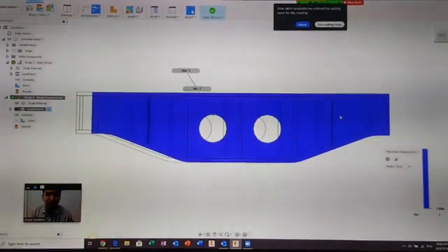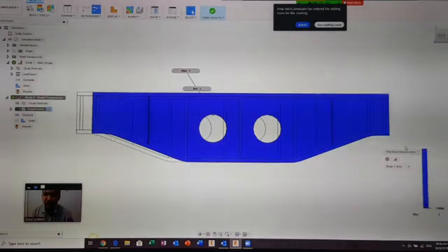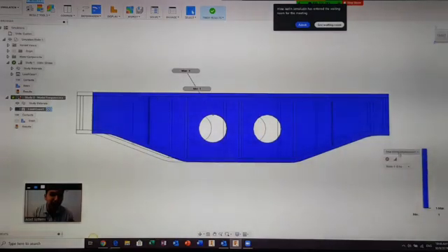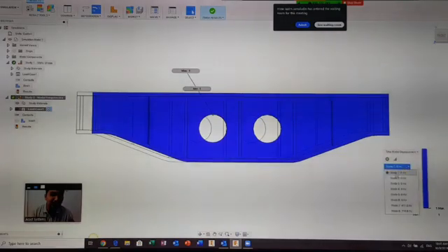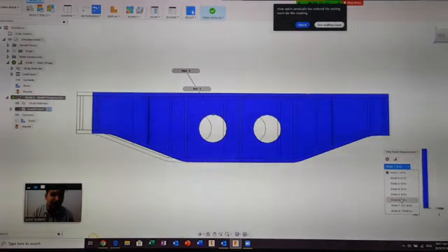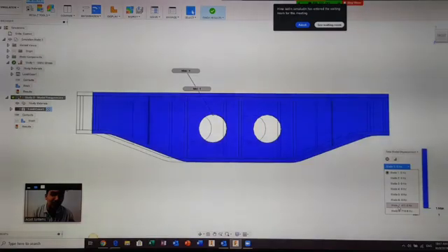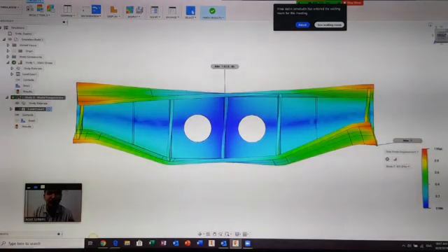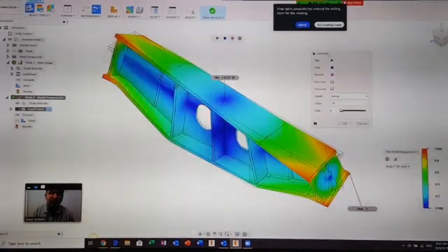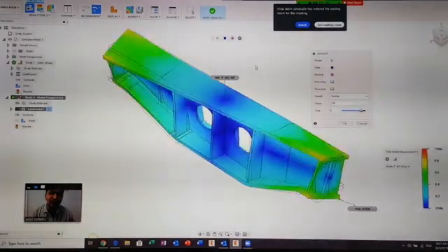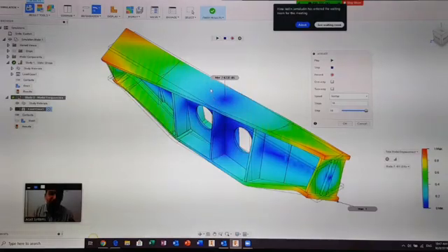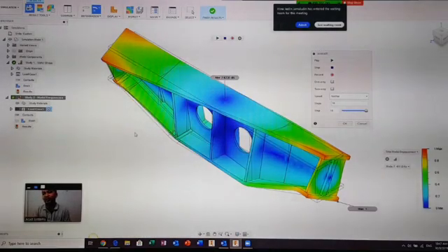Alright, so here is the modal displacement, total modal displacement. You can have the mode here. If you want to see the frequency, you can select it in here. Let's say under 411 frequency, it will happen like this. Inside the result here you can also play the animation to see how your structure will move under the natural frequency situation.